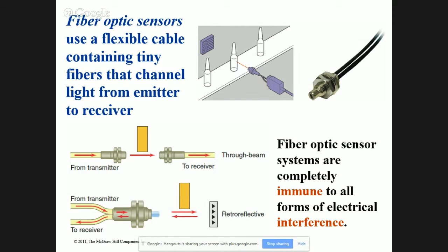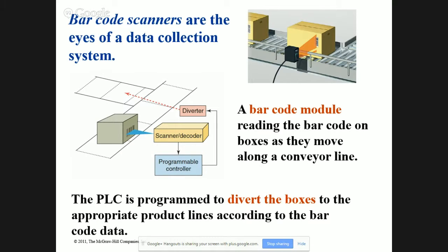They have fiber optic adapters for all of these. It's your standard photo eye. You buy the little thing, and you just snap it on the front, and it's a way to take a diffuse photo eye and make it a pinpoint, basically. Barcode scanners, we talked about that. Told you about string variables and how you pull the data into a string.